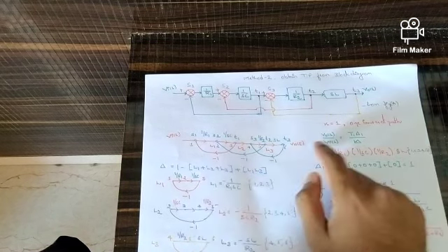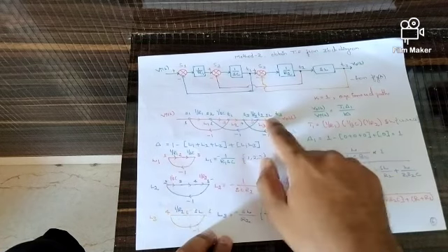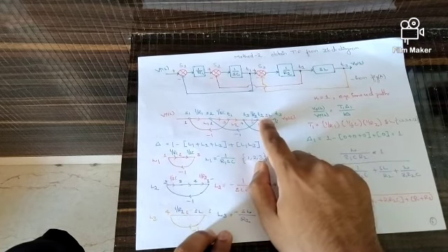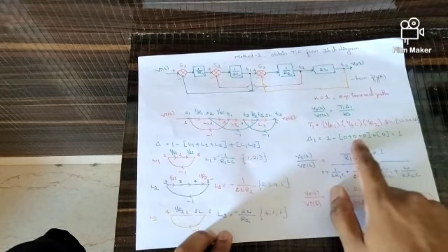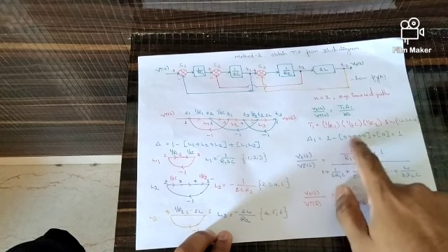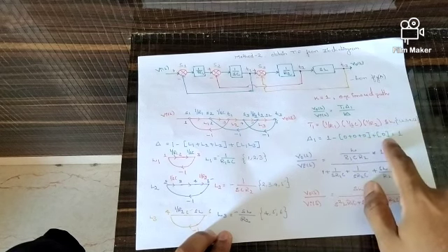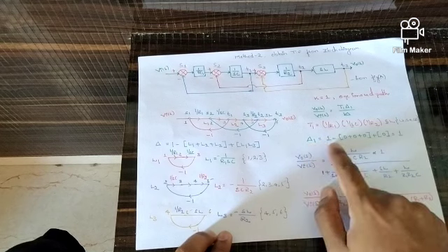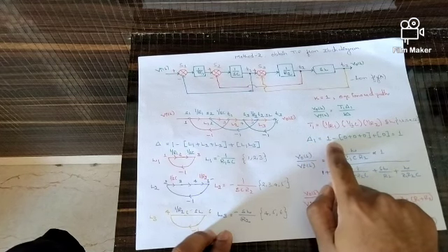As you can see, when I compare with the gain, since the gain has all the node numbers, it indicates that all the loops are touching or going along with the forward path. That means delta 1 has L1 as 0, L2 as 0, L3 as 0. Since L1, L2 and L3 are 0, their combinations are also 0. So the only leftover value is 1.